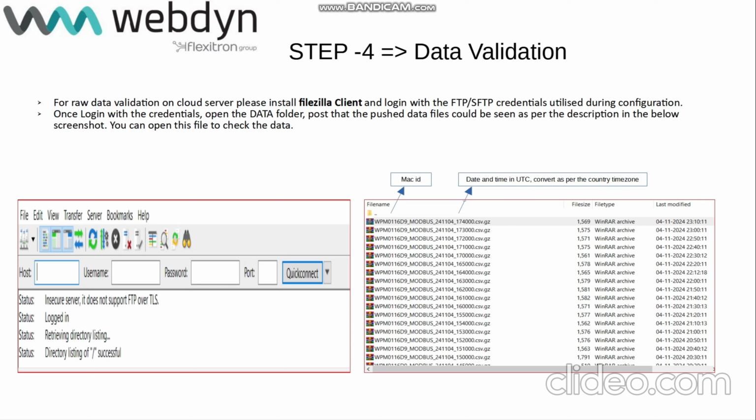In this, you will see the device index, meaning the number of devices that are there, and the device ID, which is 7, with what kind of device it is, its name, or the definition file name that you configured initially, which is Modbus sensor, so I can identify that it's a sensor, and the respective values under the headers. In the same row where 7 is written as the Modbus ID, you will see 1, 2, 3, 4, 5, 6, 7. These are the headers in increasing order of the number of parameters that you are reading.